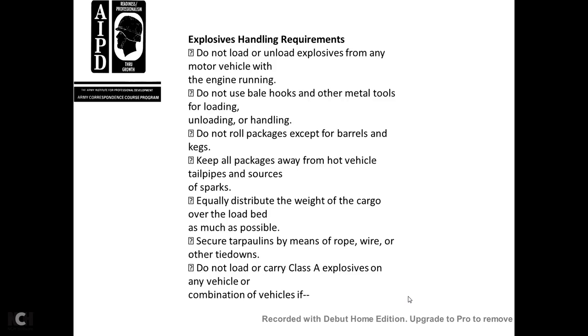Do not roll packages except for barrels and kegs. Keep all packages away from hot vehicle tailpipes and sources of spark. Distribute the weight of the cargo equally over the load bed as much as possible. Secure tarpaulins by means of rope, wire, and tie downs.